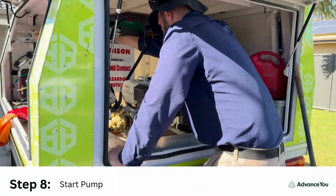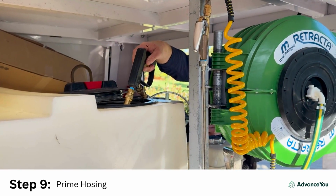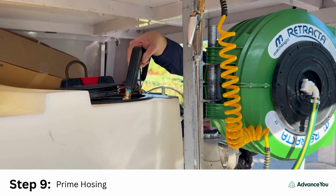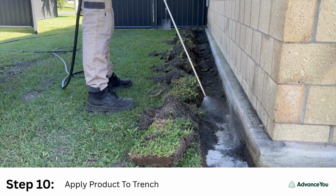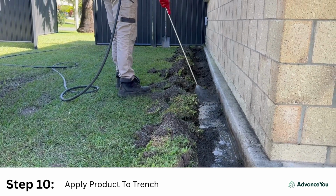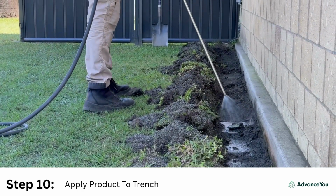Once you've finished digging your trench, start your pump in a well-ventilated area and prime your hosing to ensure termiticide is all the way through to your injection rod. Using a wide fan nozzle, apply the termiticide to the base of the trench at the rate required by the label. Use a flow meter to determine the volume as you go.